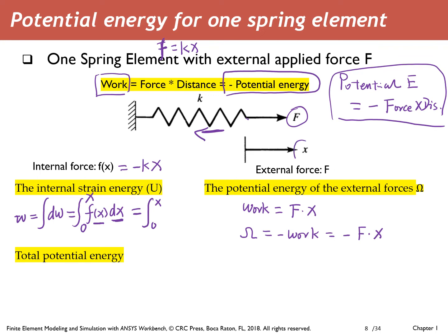So if we define x as the positive direction, the internal force is negative, minus kx dx. That leads to the internal energy equals negative work, as we defined at the very beginning, which is negative integral from 0 to x of minus kx dx.